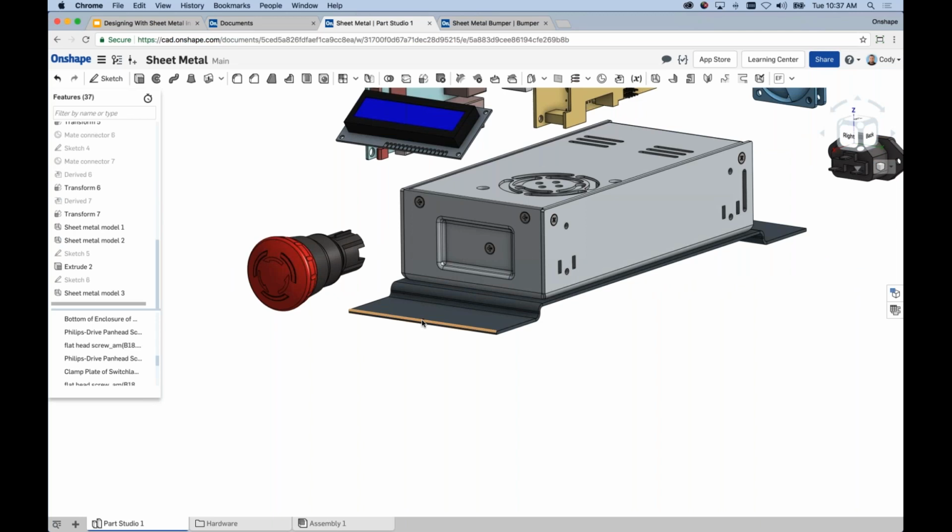Right, an open profile. So that is a technique I know a lot of users out there are familiar with, and it's a technique that is very easy to do in Onshape. So again, those are the 3 ways that we have. Just to recap, we have convert a solid, thicken a face, and extrude an open profile, as we've done just now. Now, for time's sake, we're not going to go through necessarily every single sheet metal feature, but I did want to stress again those 3 critical ways that we have to get started with your sheet metal design.